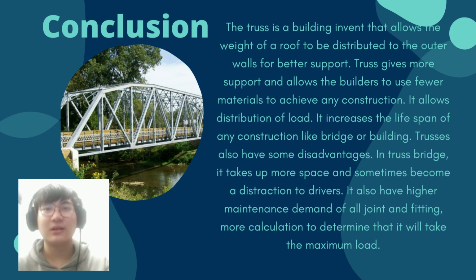Trusses also have some disadvantages. In a truss bridge, it takes up more space and sometimes is more of a distraction to drivers. It also has higher maintenance demand for all joints and fittings, and more calculation is needed to determine that it will take the maximum load.